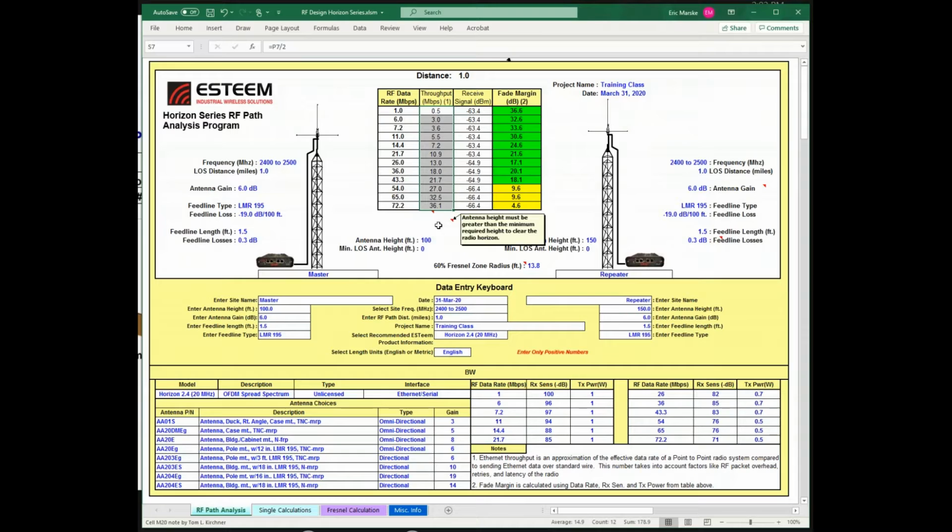There is a tremendous amount of overhead that has to happen. We have security, we have the turning on, turning off of the radio transmitter. By the time that you take all that overhead off, a good rule of thumb for any radio system is about a 2-for-1 split. So whatever you're getting as far as an RF data rate, you can expect about half of that as far as the throughput.